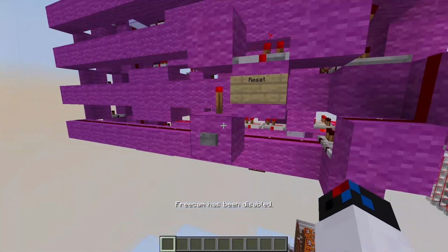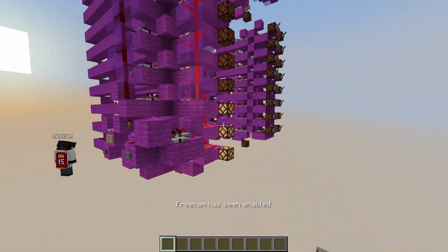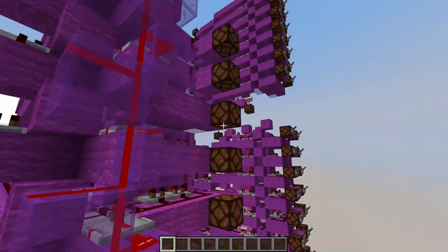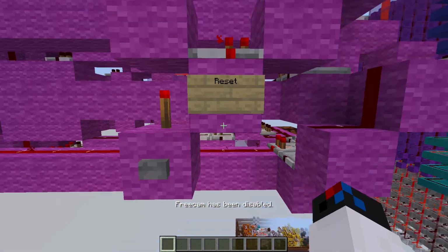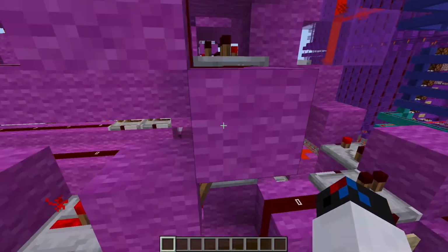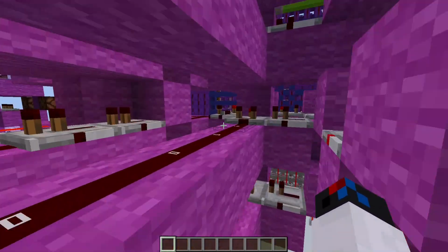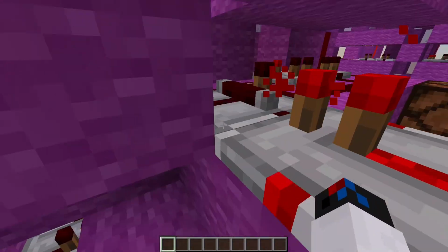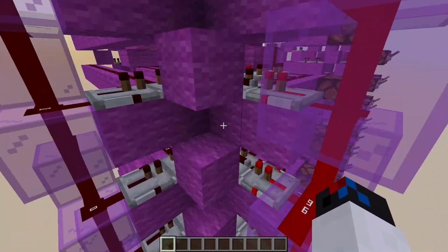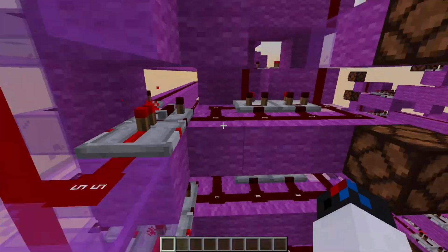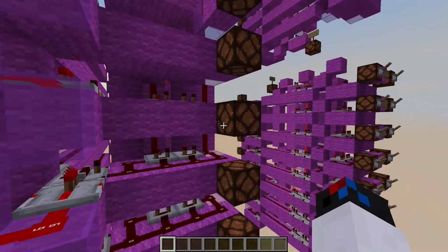It also has, like I have said, a reset button. So when I press that button, these lamps will turn off, like so. And the way that this reset button works is I basically just overwrite the output of the adder with 0, and then I unlock the registers, or all of the latches here, to basically write 0 into the register. And since they are all 0, all the lamps will turn off.